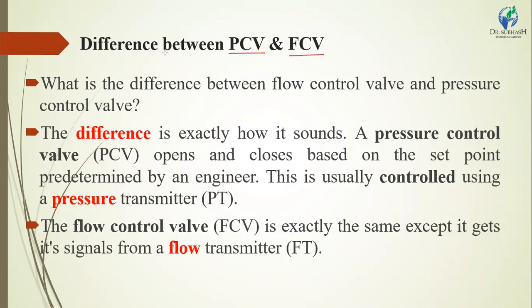If we require fast work from a hydraulic system for moving a load, like a lift system or downward system, we have to give a higher flow rate inside the system. If we have to move a lift system at a slow rate, then we have to give a lower flow rate.